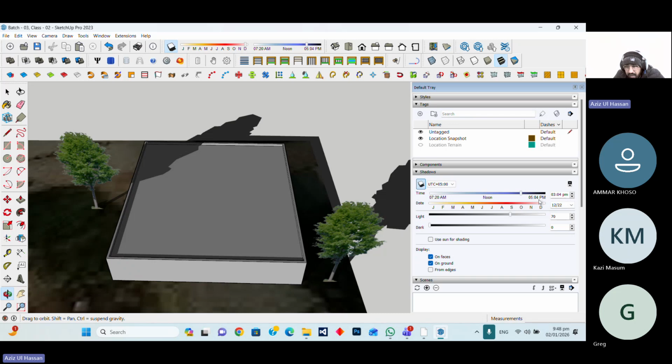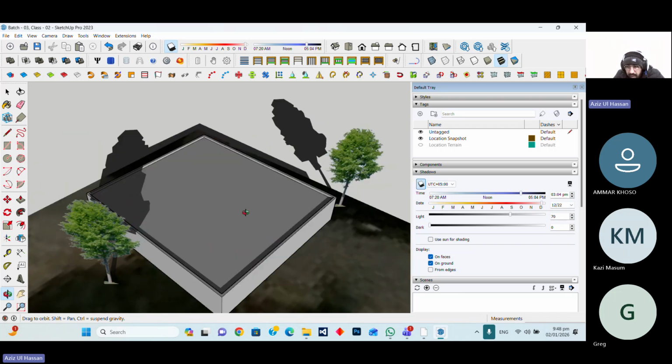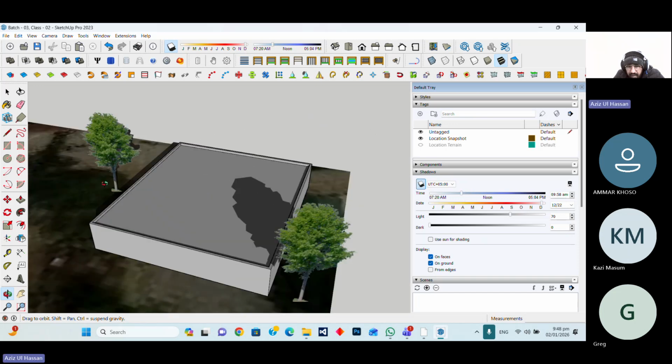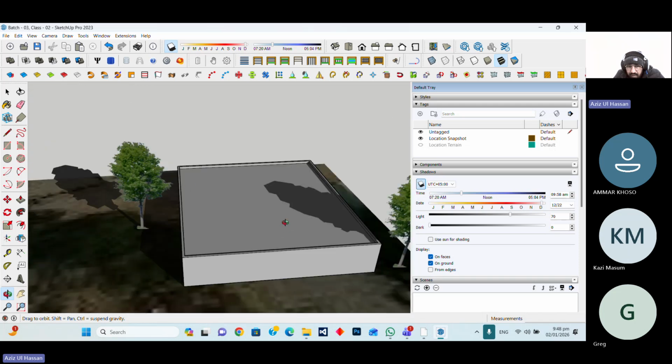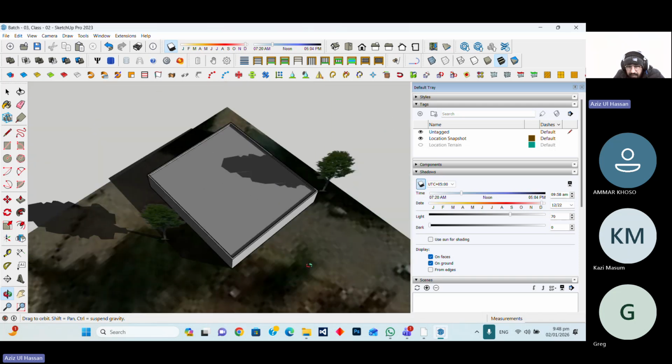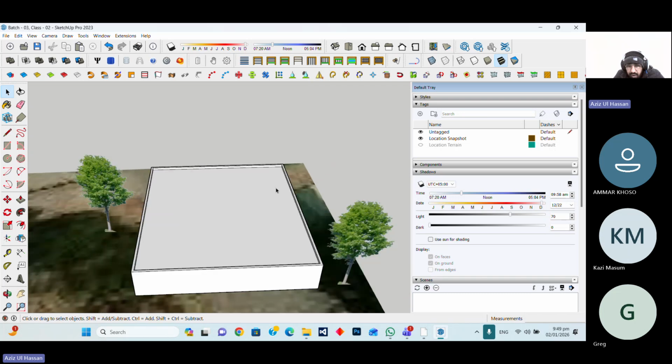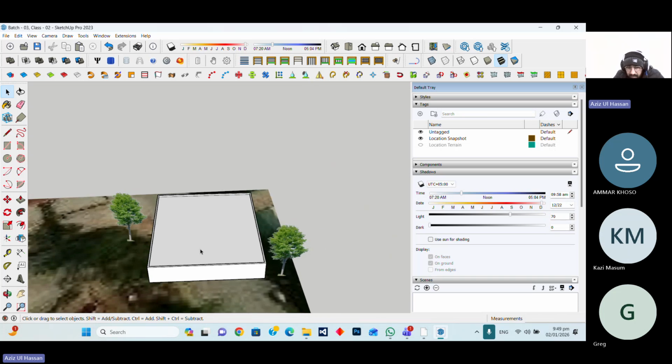I have December and 3 p.m. as the time, and in December they are creating the shadow on the rooftops. And at 9 a.m., you can see that at 9:10 they are creating the shadow on that. So we have to give the PV modules height to clear them from the shadow effects. So here we are making customized, heighted PV modules, one shed type PV modules.